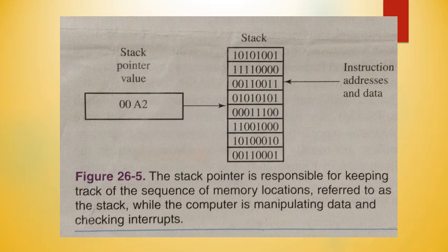Programmable read-only memory, or PROM, is memory that is programmed after it's manufactured. It is manufactured with thousands of empty memory cells. A program writer burns a pattern into the empty cells, forming a program in the blank PROM chip. Like masked ROM, a PROM chip program is permanent for the life of the chip.